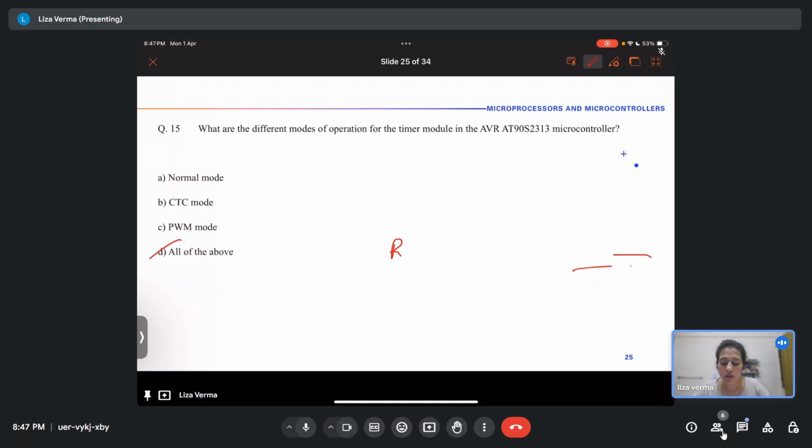For this reverse subtract with carry, the result will be stored in R0, and the result will be R2 minus R1 minus the complement of carry. Remember, in ARM instructions, carry is generated in the opposite way.